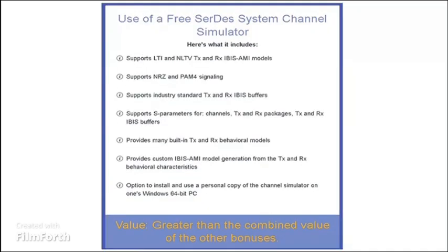You get the use of a free SerDes system channel simulator that supports LTI and NLTV transmit and receive IBIS-AMI models, supports NRZ and PAM4 signaling, supports the industry standard transmit and receive IBIS buffers, supports S parameters for channels, transmit and receive packages, transmit and receive IBIS buffers, provides many built-in transmit and receive behavioral models, and provides custom IBIS-AMI model generation from the transmit and receive behavioral characteristics.